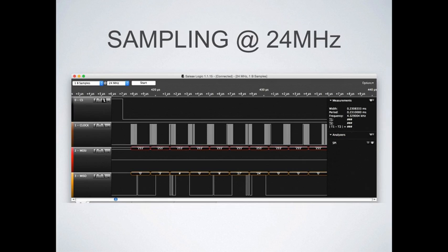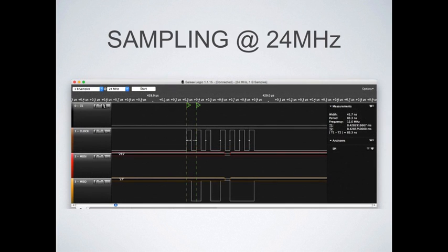the clock signal. Usually what I'll see is data, and the clock is uniform all the way across, and then it drops off, and comes back, and drops down to 0 and comes back. But you should see some clock signal all the way across. If we zoom in on this, my clock is crossing the boundary of the data line. So I shouldn't be getting that data. I shouldn't be seeing that.